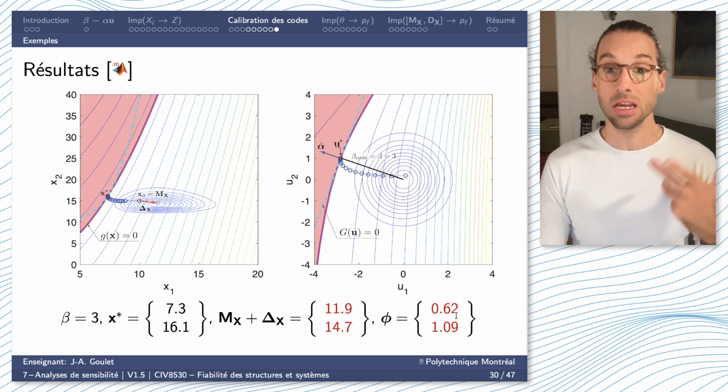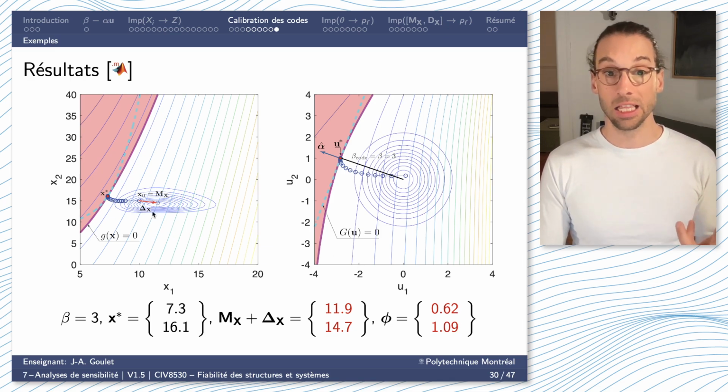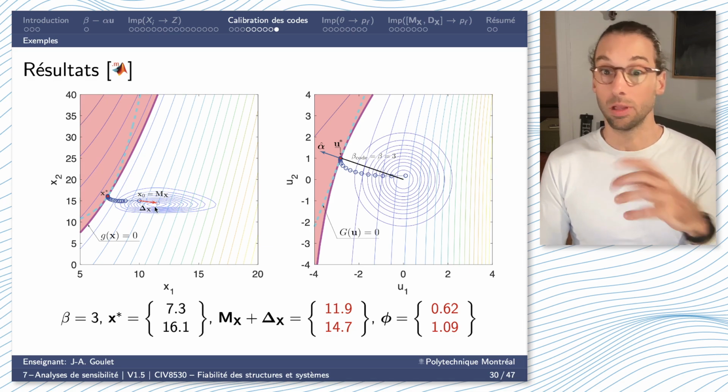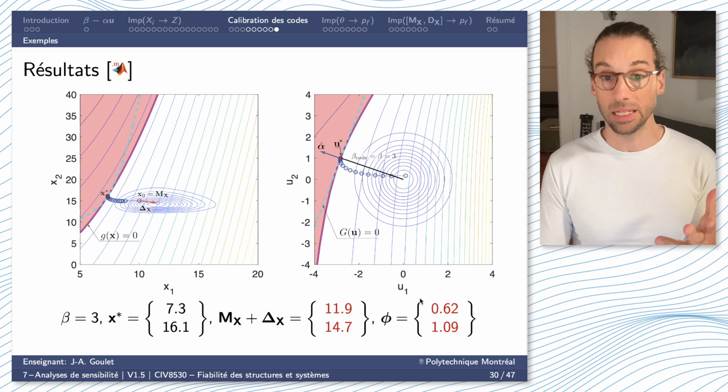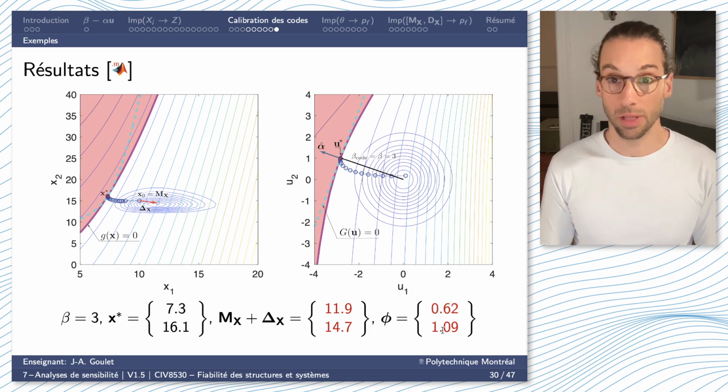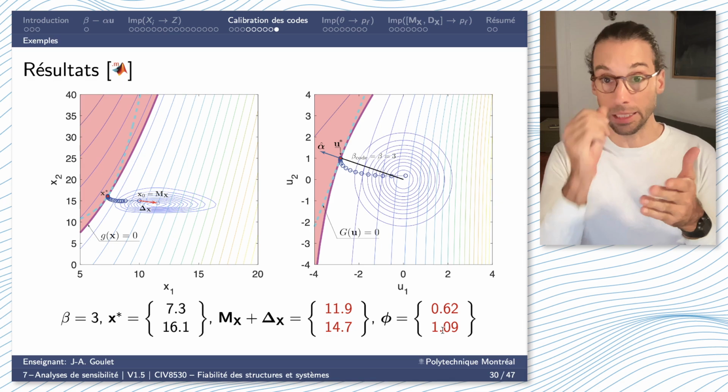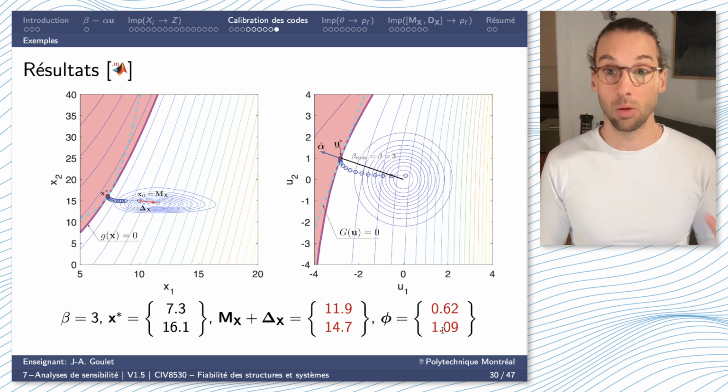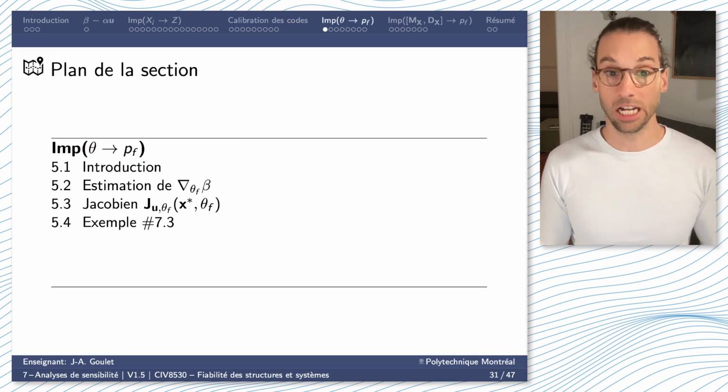So it really inherently reflects the uncertainty I have about each variable in my problem. In this case, dimension is a lot more uncertain than solicitation, so it's the one that's going to be driving my uncertainty in my reliability index. That's why I have a higher correction on the dimension than on the solicitation. That procedure automatically tells you which variable should be weighted by what quantity in order to satisfy your reliability index specified in the code.